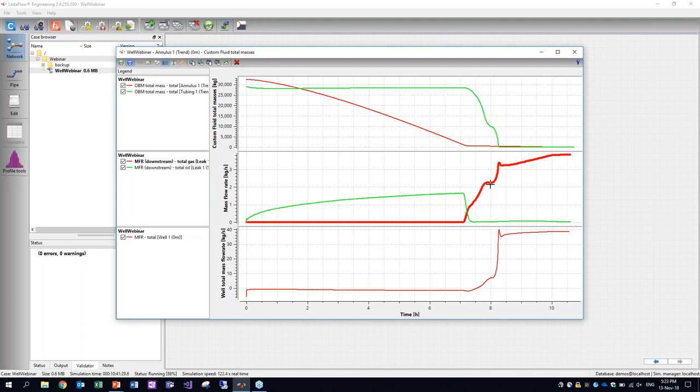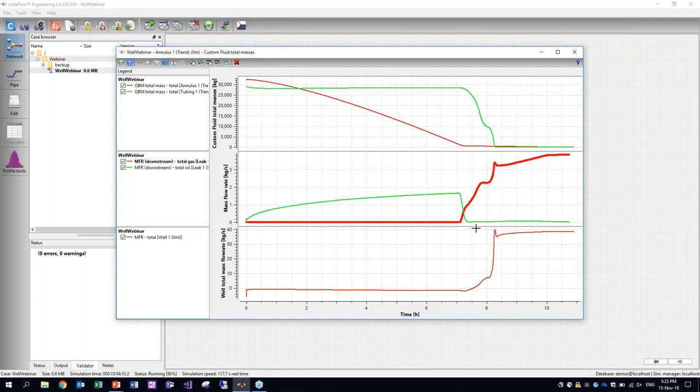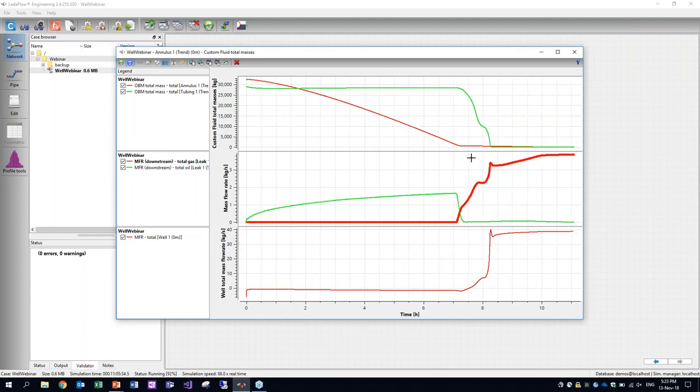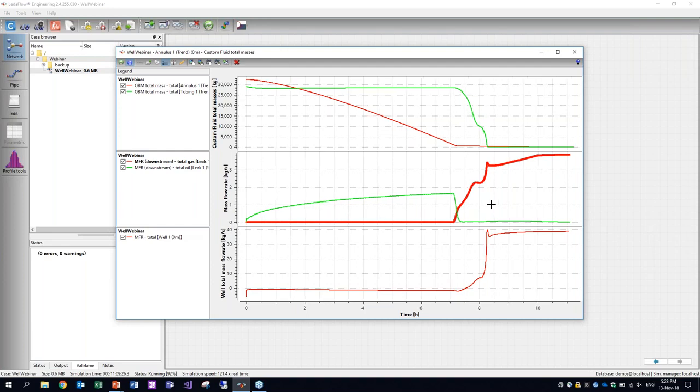So we're immediately pushing gas lift quite deep in the well, and it's very quick to push out a lot of the oil-based mud from the well. Plus it also has the benefit of getting a nice push from the reservoir. So it's very easy to get it started then.